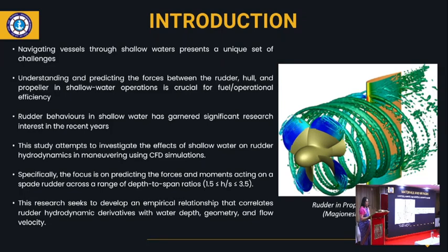So if I give you the equations of sway and yaw in maneuvering, we have some hydrodynamic derivatives. Some of the hydrodynamic derivatives were introduced by my NSTL friend, Rahul Kumar. But I would like to give a manifestation of these hydrodynamic derivatives, which is very important from my work's point of view. There is Y_v dot, which gets added to or subtracted from mass, and is manifested as an added mass component. And there is Y_v, the velocity dependent derivative, which is manifested as a damping coefficient.